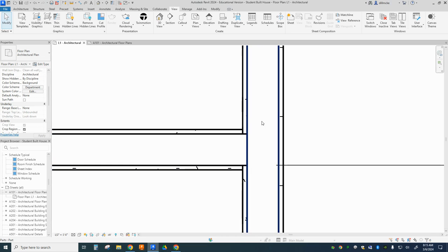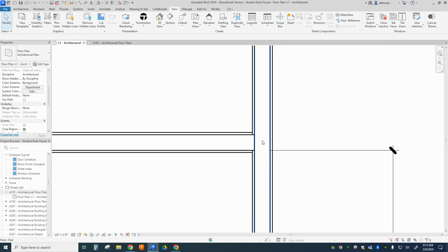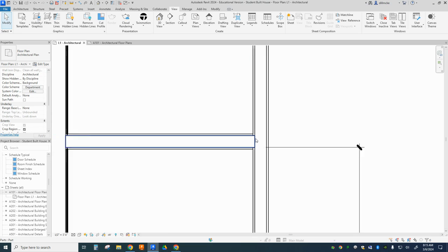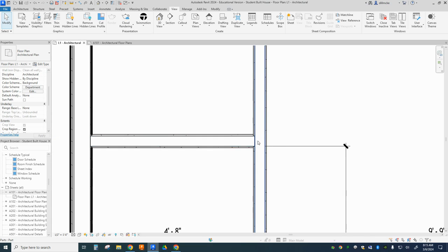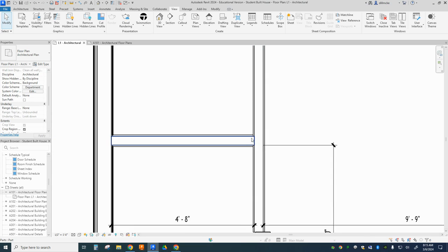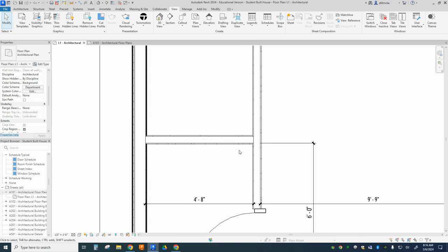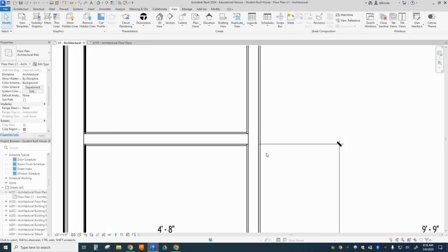And where two walls meet each other, you get a more accurate representation of how the parts and pieces of the wall actually fit together. So this is a useful thing to be able to see, but in this step we're actually going to hide the parts of the wall that aren't framing. So first we have to create parts. That step is what makes this very difficult to edit. Once you've made a wall into just parts, changing the dimensions is not as easy as it used to be. So definitely wait to do that.